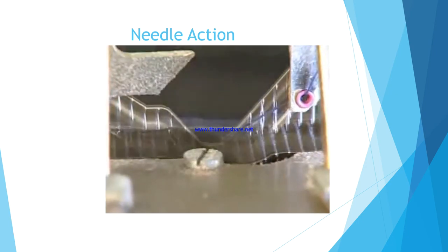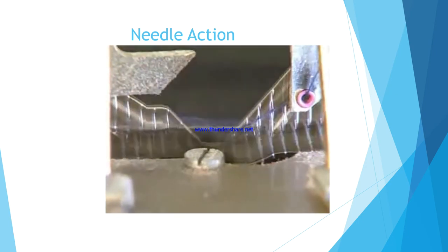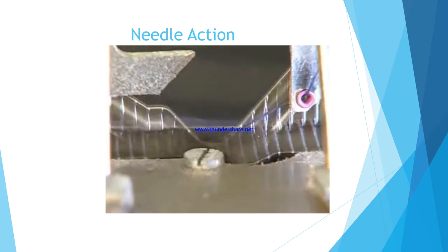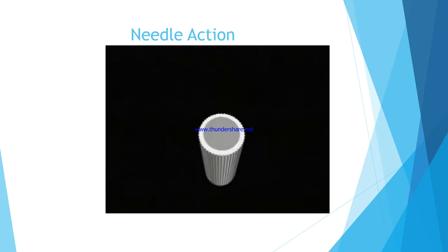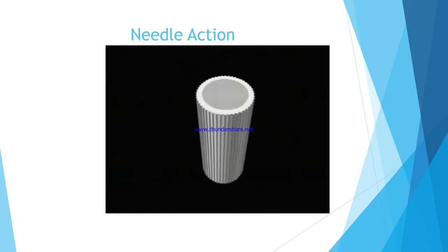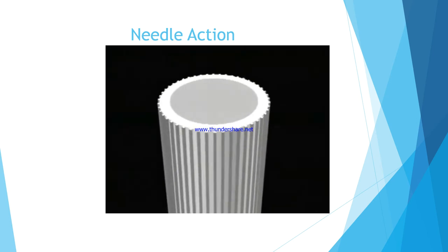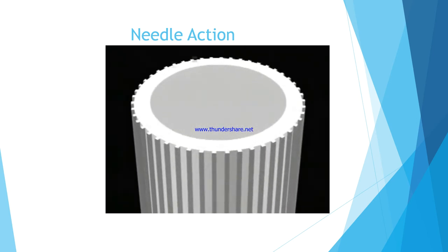In this segment, we describe how needles actually do their work. How are the needles arranged, and what causes them to move? Knitting machines are designed so that each needle can be placed in a groove, cut into the outside of a metal cylinder. Before we show you how these cylinders work, let's define the parts.